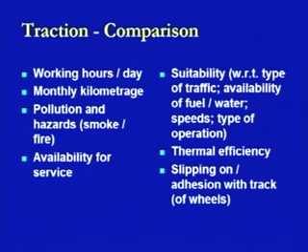The adhesion or the slipping of the locomotives on the tracks is a sort of interaction between the wheels and the track being laid down, and the values remain more or less similar depending on the type of the electric or the hydraulic traction which is being provided, and it varies between 0.22 and 0.33.